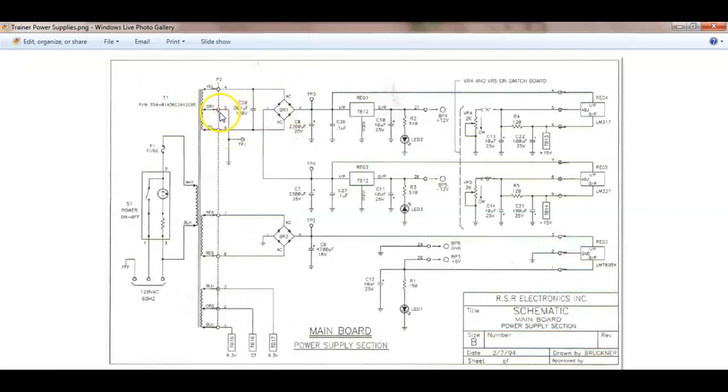Now what the telltale sign is, notice what's missing here. Well, this guy's got this center tap connected to common. And notice this guy here does not have a ground. It's got a ground over here, but all these guys, this is not ground. They didn't bring it through, right? You understand that? So it's technically a common. So what we have is this is my positive power supply right here. And then this right here is my negative power supply right there. You understand that? Yes or no?